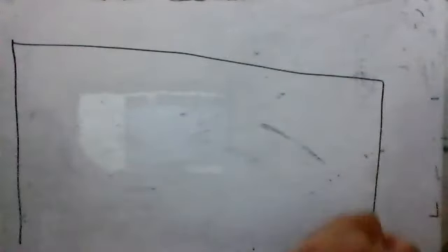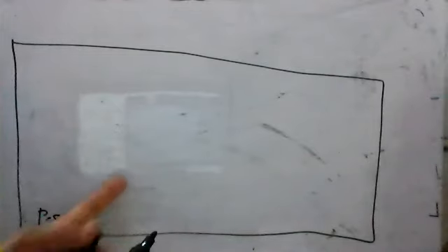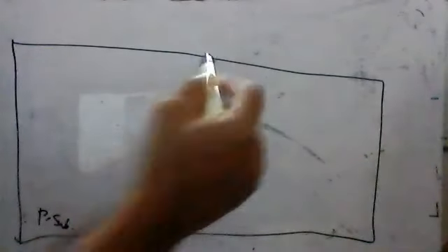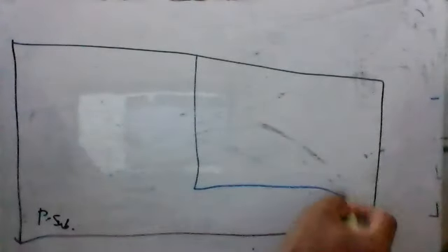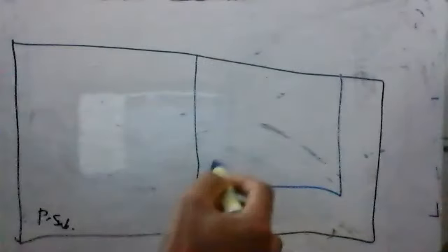Physically, first we take a bigger piece, because we have to make a whole CMOS in here. One substrate is a P-type substrate. P-type, right? Inside the P-type, we have to make an N-type region. In half or almost half of the area, we put N-type.